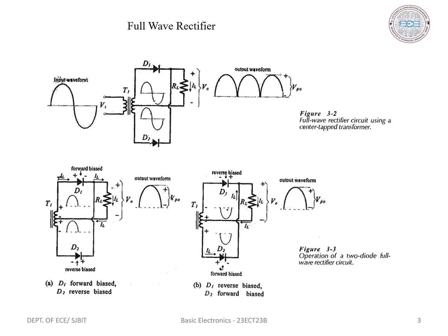But during the negative half cycle of the AC input, the voltage at point C is positive and point B is negative. Thus, D2 is forward biased and D1 is reverse biased. Now it is the complementary operation, because of which the current flows through the load resistance RL here. So during the second half cycle, D2 will be in an on condition and D1 will be in an off condition, but still the current flows through the load resistance RL.